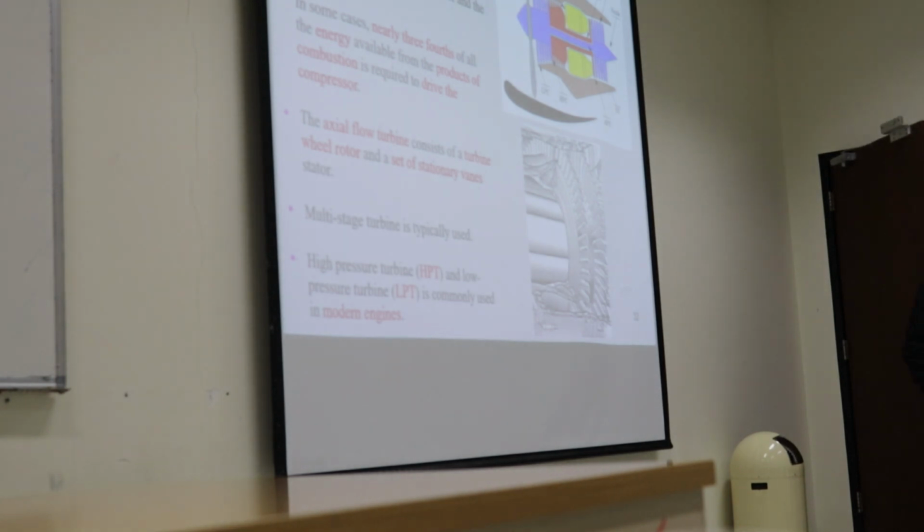I don't think it is a mid turbine. They use a kind of reduction gear, as a matter of fact. It's 3 shafts, right? High, low. Also, in the Rolls-Royce on the Airbus 330, they use something called the middle shaft. Maybe this is for startup or to drive some other accessories, but it cannot be a shaft for a 3-stage turbine and 3-stage compressor.